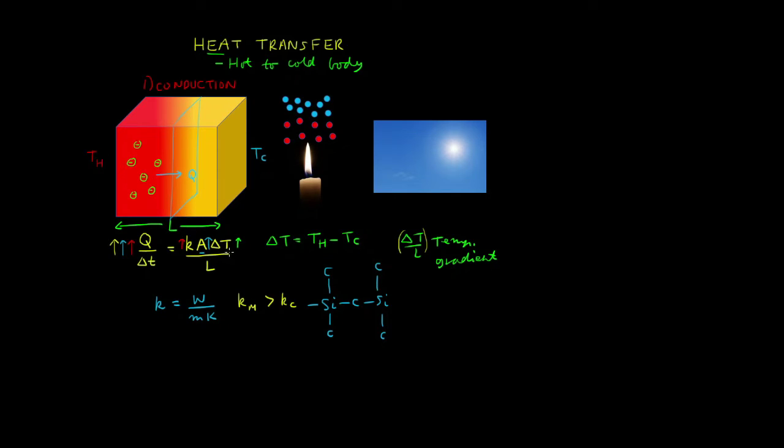And if we look at these quantities individually, well, a larger difference in temperature will give you a higher quantity for delta T, which will also yield a higher rate of heat transfer, whereas the distance through which heat has to travel through the material, denoted by L, if this quantity is higher, then that's going to result in a lower rate of heat transferred through the material. So really have a think about this, and now we'll move to the second mode of heat transfer, known as